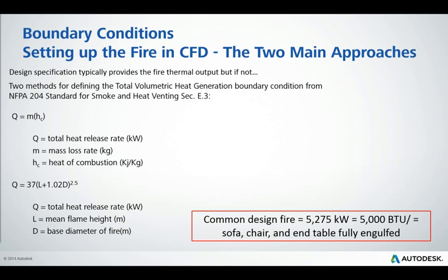But what I would mention, I guess, is if we don't know from a specification what our heat load is, we normally do, and we normally apply that to the volume. And there's a couple of equations here that we can use if we happen to know a mass loss rate or perhaps the height of the flame in conjunction with the size of the fire, so we can get an idea of what the heat release rate or the energy.